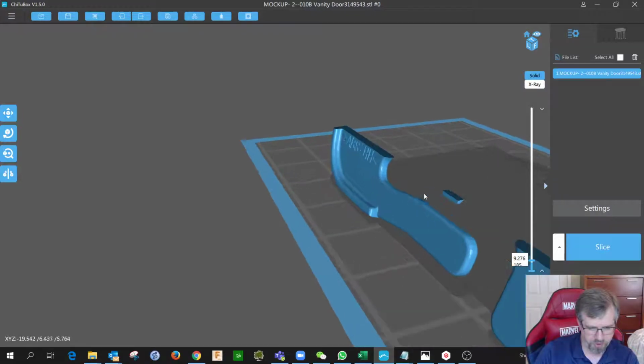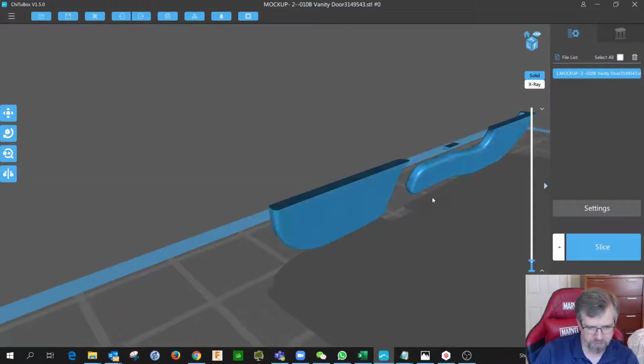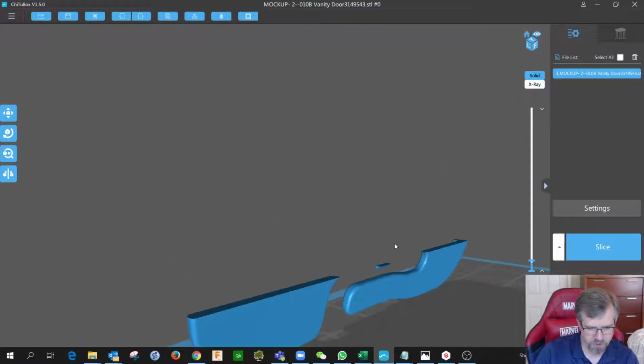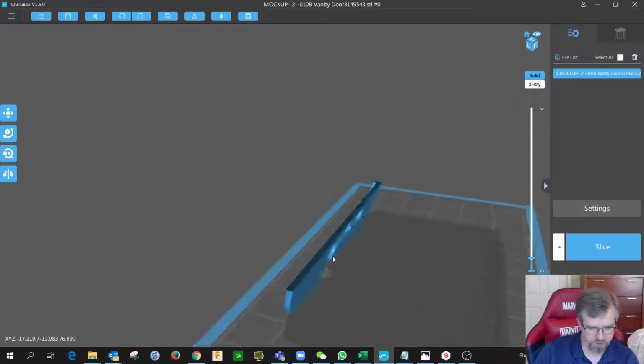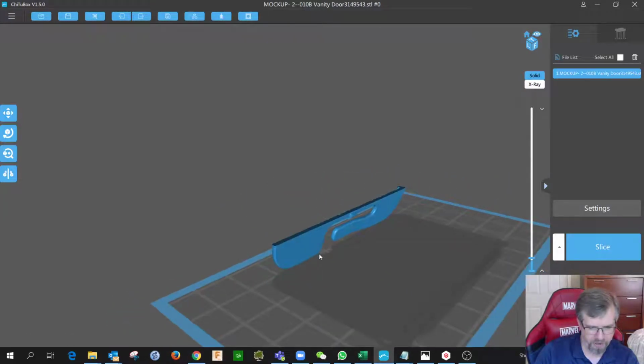Now here's another spot. So look at this little snap feature, or this little ramped feature, another unsupported island. That's going to be a problem. So that's not going to generate, or that's not going to stick to the part. It's going to get stuck in the vat.